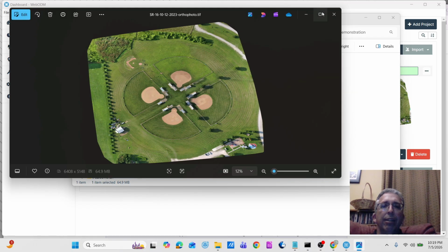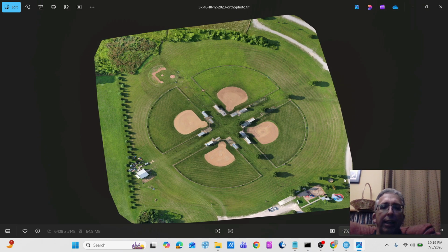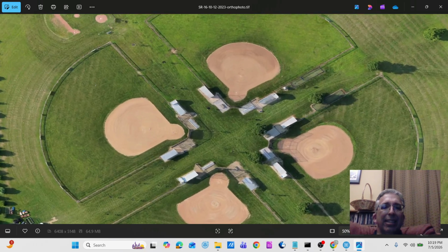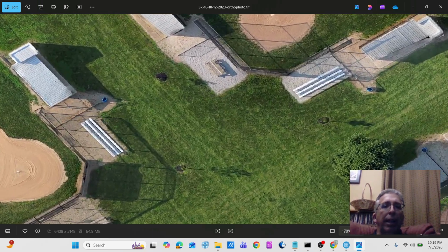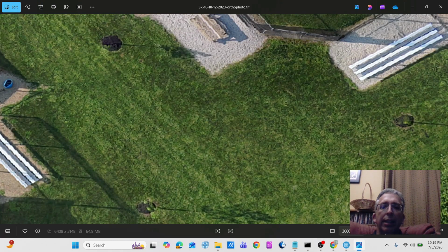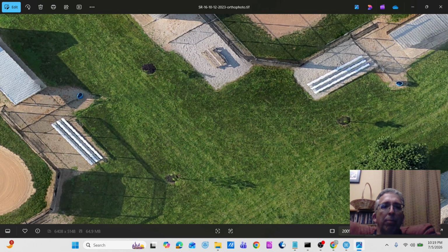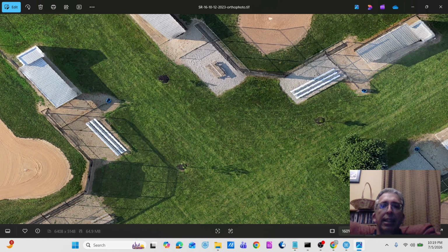this is what the file actually ends up looking like, and you can zoom way in on this. And it's a little distorted by the latitude-longitude transformation because latitude and longitude are not the same number of miles depending on what latitude you're at. But we like the view, and if you bring it into a tool like QGIS, it will show its coordinates in latitude and longitude, which makes it easier to pull lat and long off of clues and things like that. So frequently we save in 4326 format.